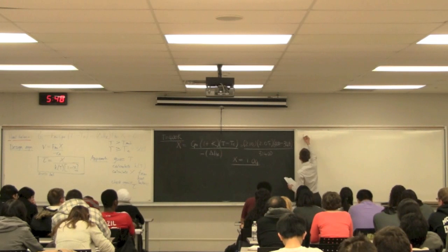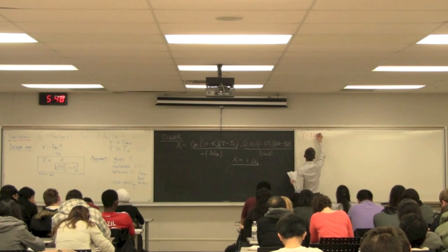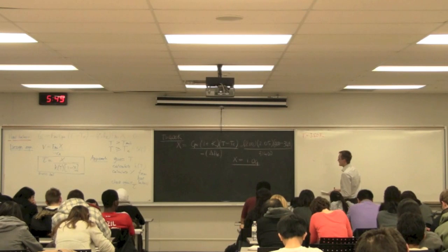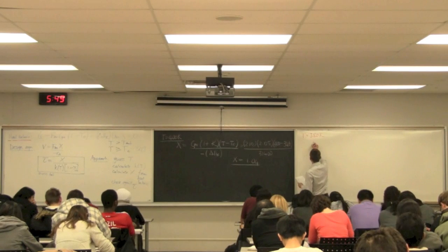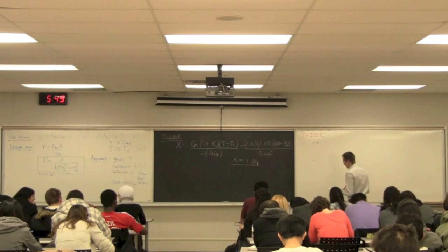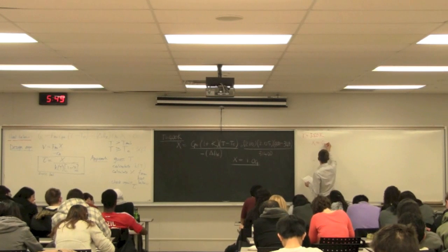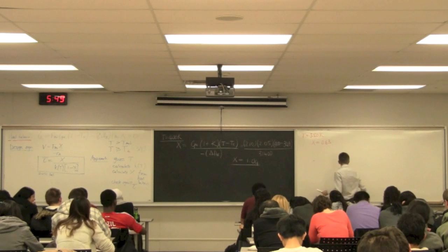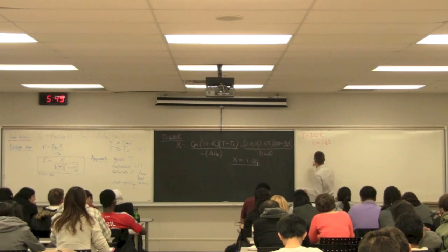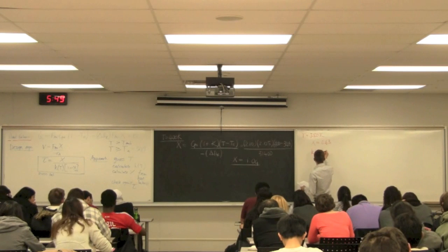So 380 Kelvin was my next guess here. We said let's calculate that conversion again, so I won't sub in all the numbers, but using that same equation over there, the conversion you can calculate for yourself is 0.63. I can also then calculate the rate constant k(T).